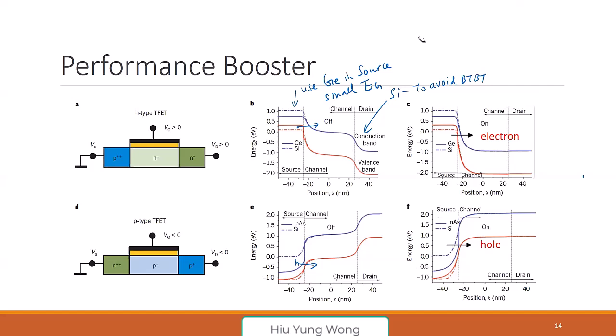The electron can go to the gate easily. You don't have an insulator because now you are in vacuum. You can go to any material. Think about a molecule in the air: it can stick to anything in your room. So there's no insulator, and I get a lot of gate leakage in my simulation.